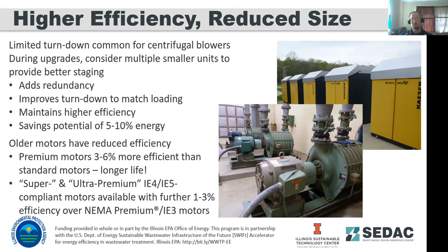They are a little bit more expensive. I know the IE4 motors are designed to be cost competitive with NEMA premium. The IE5 are a little bit more expensive than that. But again, with better materials, with better windings, better, smoother bearings, on top of the energy efficiency increase that you're going to get from those systems, you're also going to get a maintenance durability increase. So on top of improving your energy efficiency, you're also going to be reducing your maintenance hours on those systems.